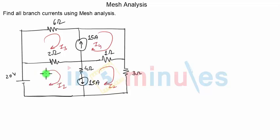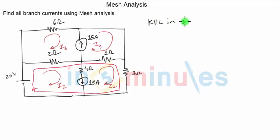You can see I can't write individual KVL equations because there's a 15 amperes current source which is being shared by both the meshes. So we will have to consider super mesh analysis. So this is how I'll define my first super mesh. So starting from 20 volts, let's see how the KVL equations will look like. So KVL in super mesh 1, 2. So I'll start from 20 volts. I'm going from negative polarity to positive polarity and hence there is rise in voltage.